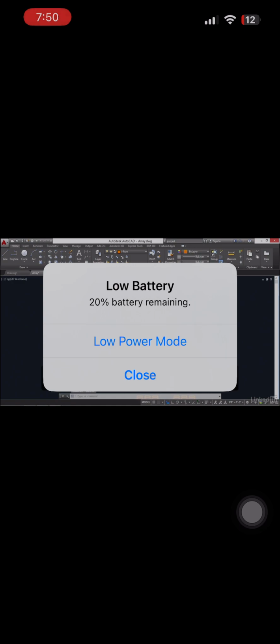I can then also go back and change this and click here on item count to have AutoCAD automatically calculate the number it's needed to maintain this distance between. And maybe I'll also choose to align the objects. That doesn't look so great. Let's go back and specify maybe 8 items and then close the array.